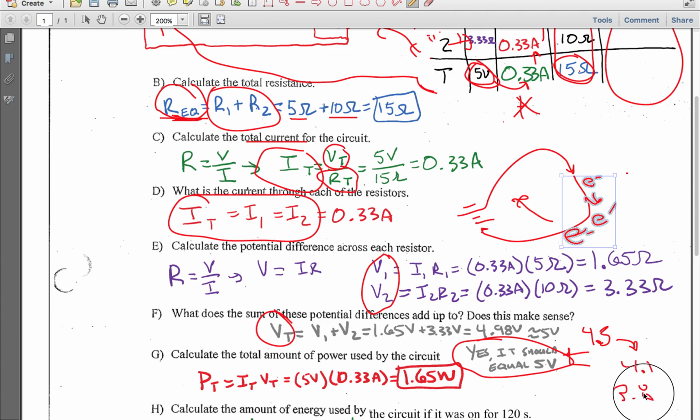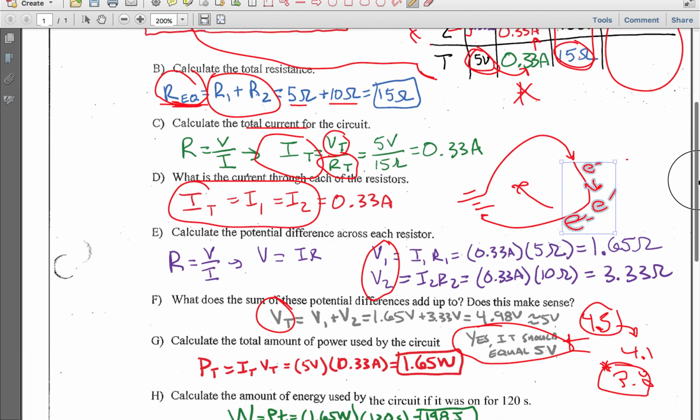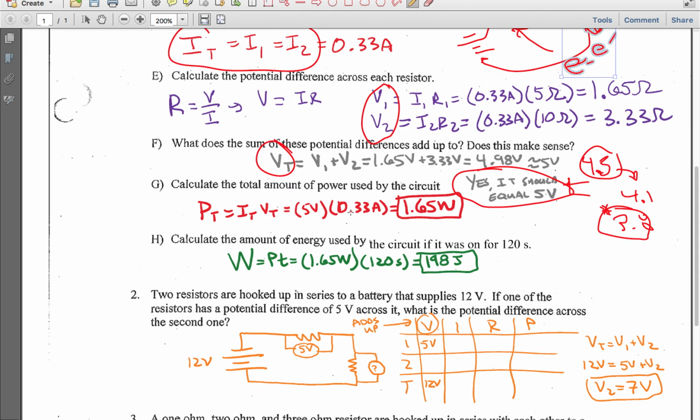And what was really interesting is the second video was 3.8, which means those wires may have heated up a little bit, and we may have had a loss in voltage as the material's moving around. I'm unsure of that. One of the batteries could have been on its way out or dying at the time that I plugged in all three to give me the total voltage being almost 0.7 volts lower than what it should have been at 4.5. So it was either a battery issue or a connectivity issue.